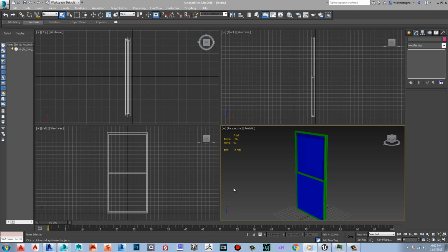Now in Revit I used feet, but it didn't matter because once it was imported into 3ds Max, I had already set up my customized settings so that any model that was imported, the unit size was respected. But at the same time, if you bring in feet, all it's going to do is add up the centimeters so that it matches the feet height and width of whatever you're bringing in, so it will be the size that you intended.